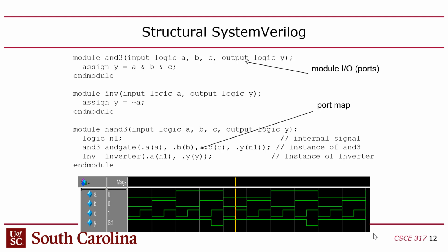But it's pretty simple. You just set it up and then you can monitor things. The problem is every time you want to add probes, you have to recompile your design and reprogram the FPGA. You can't add them after the fact. They have to be burned into the design, so to speak, because they're actually memory components that you're adding.